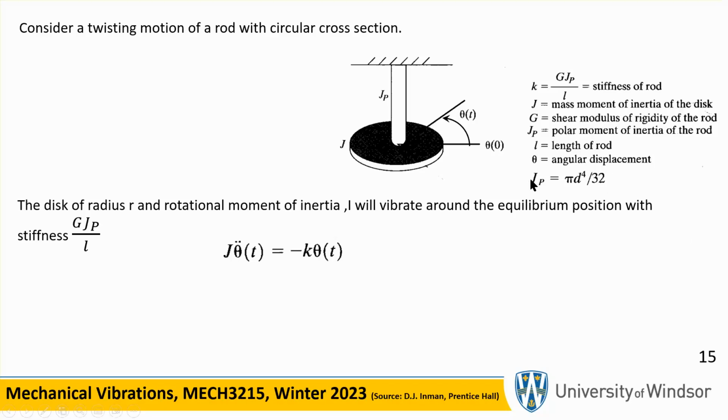So the polar moment of inertia of the bar is there. If you insist on using the formula 1/2 mr squared, you're talking about m of the bar, r is this radius, which is d over 2, etc. Just be careful. And of course, this is the inertia, and you clean it up, you get this.